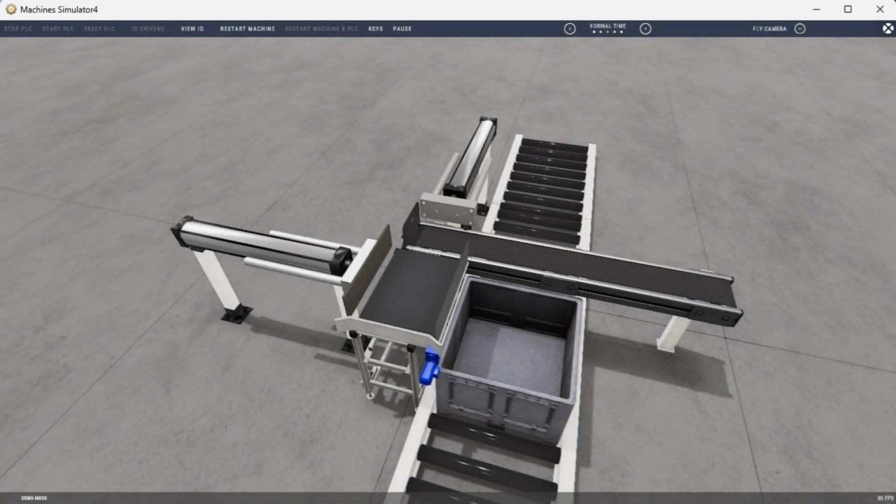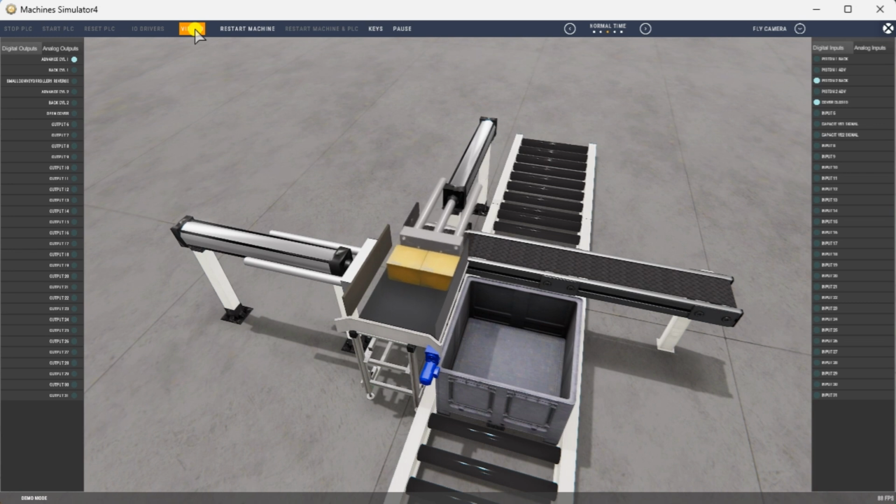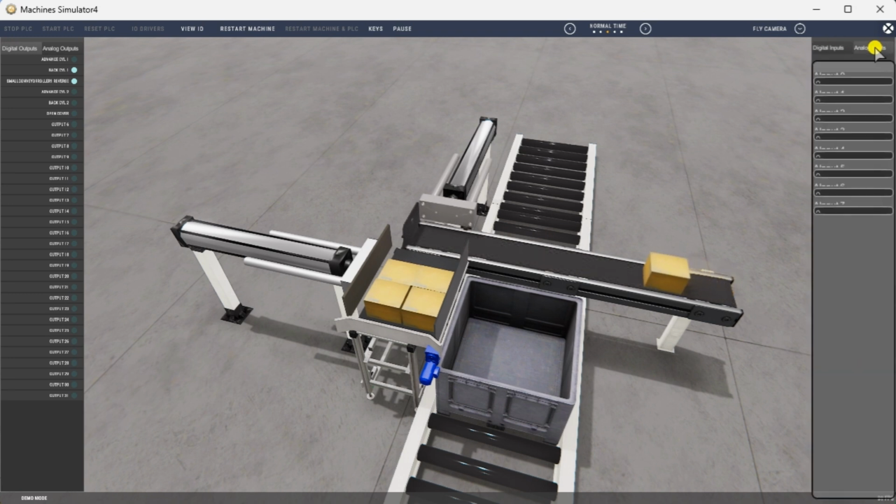When 2 boxes are collected at the end of the small conveyor, the conveyor will stop. Both capacitive sensors will be on, indicating that the boxes are present. The cylinder 1 pneumatic pusher will advance for some time or until the piston 1 advanced sensor comes on. When cylinder 1 retracts all the way, the small conveyor will start loading 2 more boxes again.